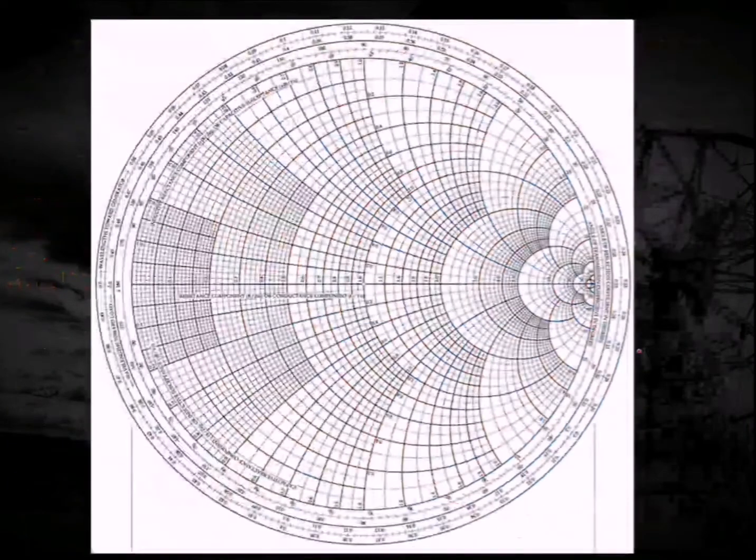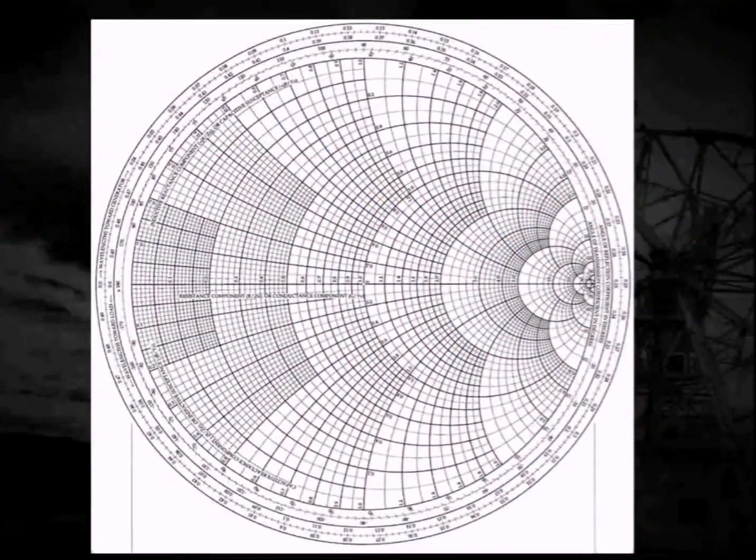Now, this is the combined Smith chart, or a professional version of the Smith chart, in which we can see these resistance circles. You can read over here the scale of the resistance circle. For example, this value is 0.1 over here. It means the value of RL over here is 0.1. This value is RL equal to 1. And if I move to the right-hand side of this, I will obtain the higher values of RL. This is 2, this is 3, and so on.